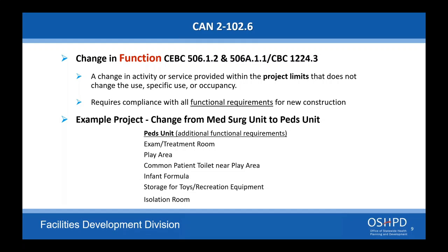Great, and if we can provide the code section here for 407.4.1, it's for those that don't know, direct access to a corridor from a habitable room. Yes, correct. And it reads habitable rooms in group I2 and I2.1 occupancy shall have an exit access door leading directly to a corridor. And there are exceptions. So if you're interested, do look up that code for those exceptions.